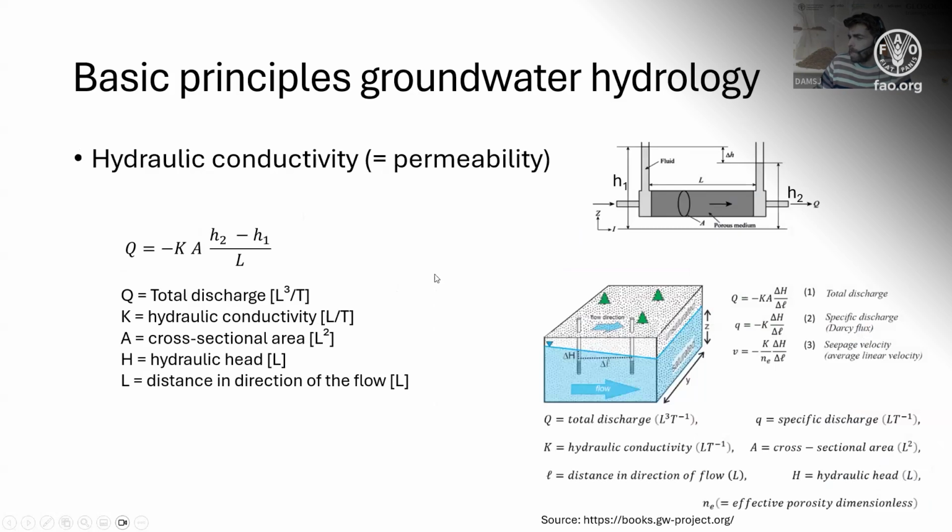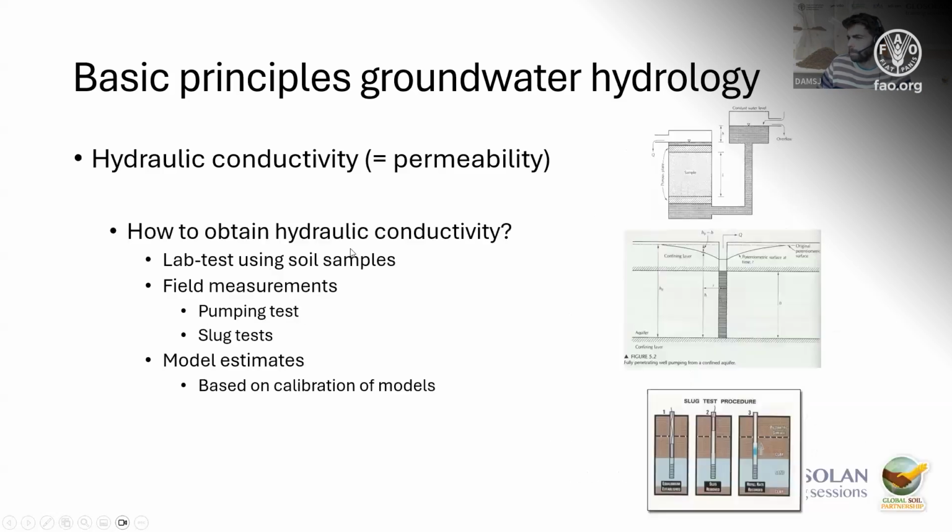Then the transport is generally regulated by the hydraulic conductivity of your aquifer system. I think in the presentation of my colleague Jan Bransers, he also mentioned Darcy's law, which is very often used in groundwater transport. So the hydraulic conductivity is in fact determining, together with the difference in hydraulic heads between the two parts, how fast the groundwater flow will be in your aquifer system.